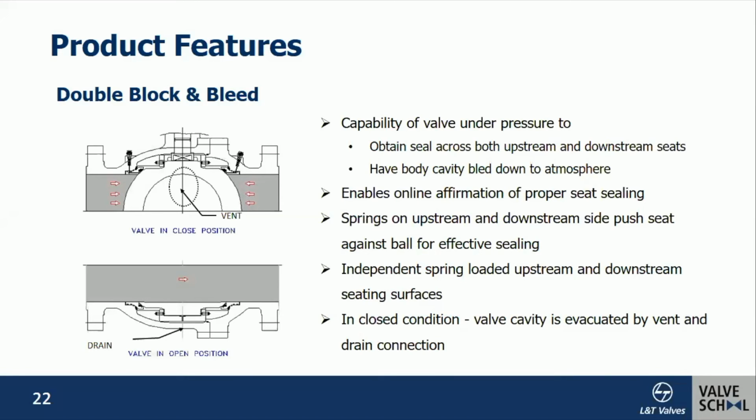The added thing is, even in the valve fully open condition, there will be no passage of the media from the bore to the cavity, so that it can be checked online. It enables online verification of the proper seat sealing. In the closed condition, the valve cavity can be evacuated by the vent and drain connection also.